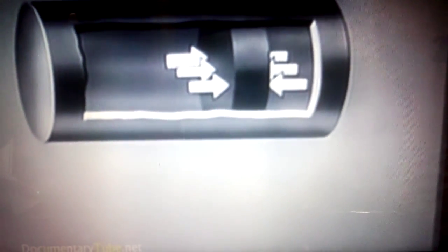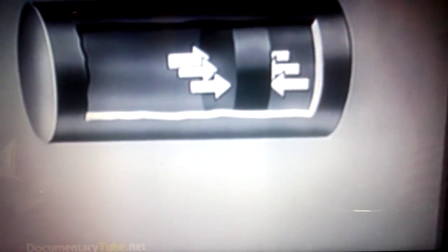Now inside the power cylinder, as you can see, there is a block which can be viewed as a piston with the same pressure on both sides as of now. Now when the pressure is increased on one side of the block more than the pressure on the other side, the block will move in one direction. As you can see, it is moving. It will move till the point when the pressure on the other side of the block overcomes it, reversing the direction of motion. So this provides a reciprocating motion to the block, and the block further steers the wheels.